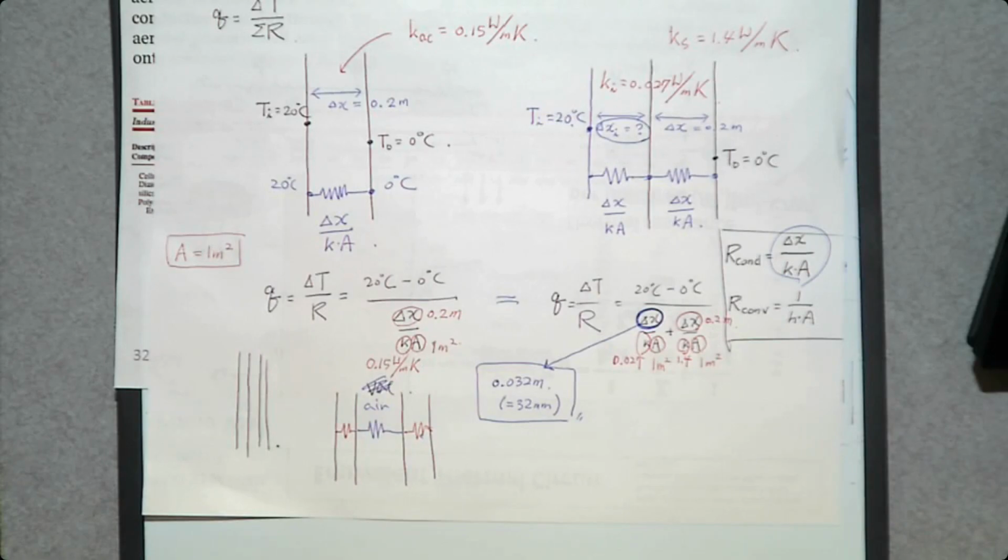Convection between the surface and the air inside, and another convection between the air and the surface here. Then is there a significant fluid movement? Not much. It's very quiet. So the convection heat transfer is very small. Of course, it is not as good as vacuum radiation, but still, it can minimize the rate of heat transfer.